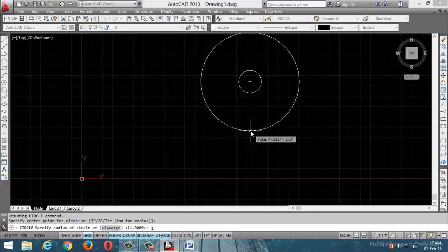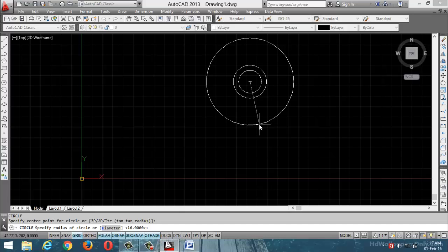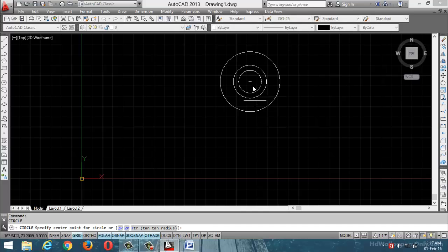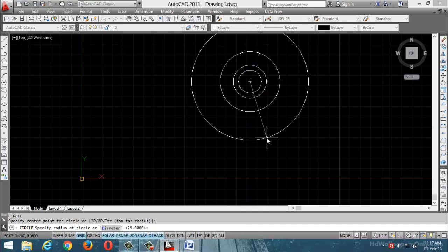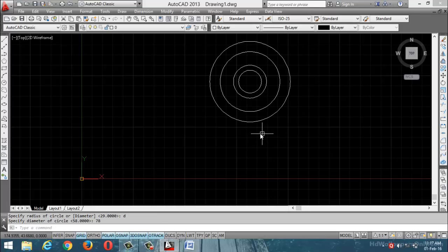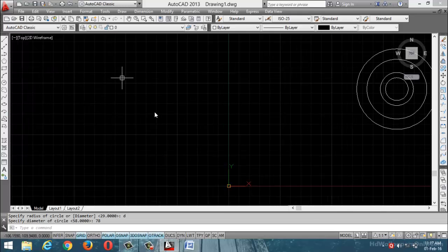16 radius, or otherwise you can activate the internal command diameter, then you can enter your input value in the format of diameter, 16. Then again next one more circle, 58. So okay, directly activate the internal command 58. Then next, 78. Okay, circles is over. Next, what is the next one?